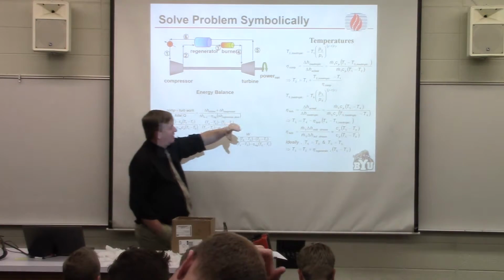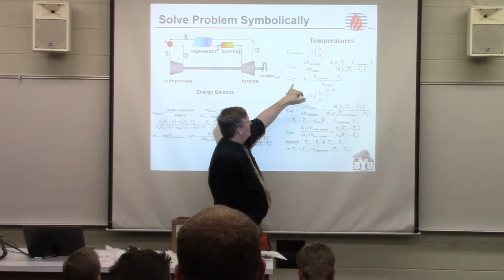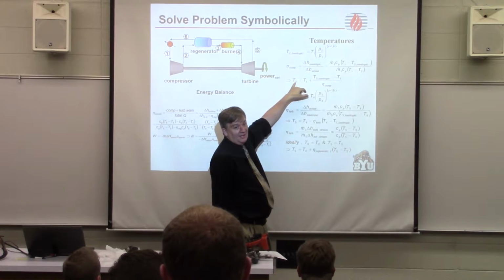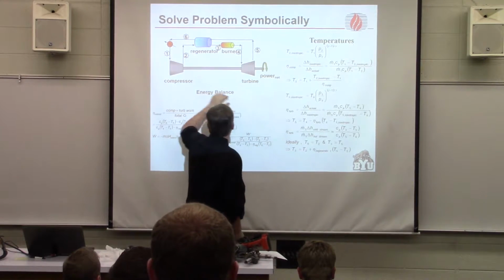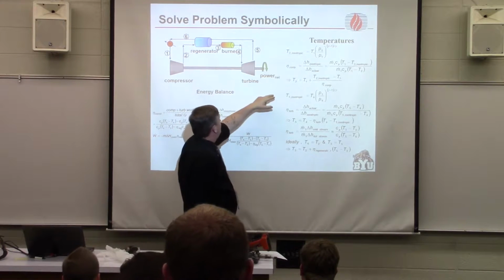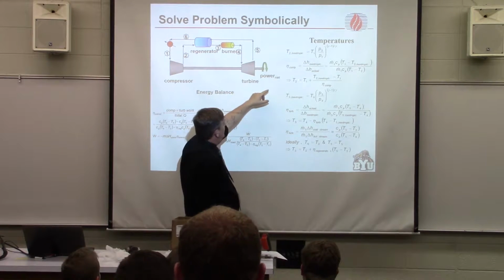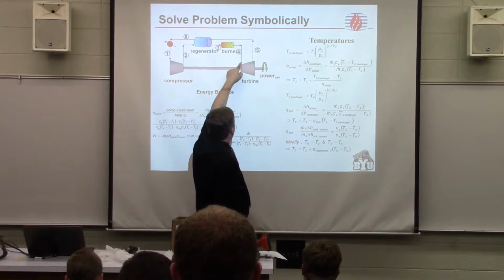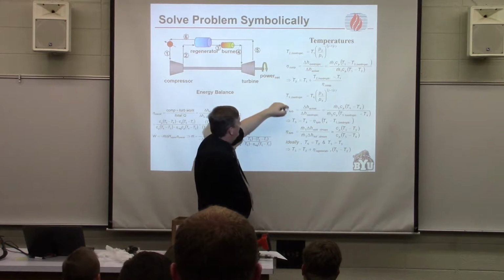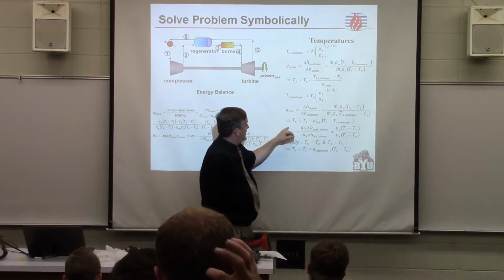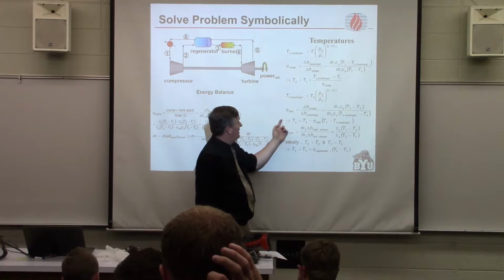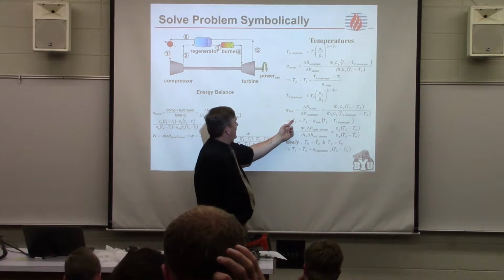So the compressor efficiencies are given in your homework assignment, but you can see how you can calculate the outlet temperature from that, right? So now we know T2, then we need to figure out T5. We go through a similar analysis, and T5 is going through a turbine expander now.